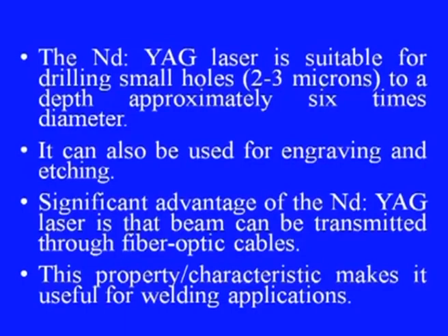The Nd:YAG laser is suitable for drilling small holes, say for example 2 to 3 microns diameter to a depth approximately 6 times the diameter. It can also be used for engraving and etching.